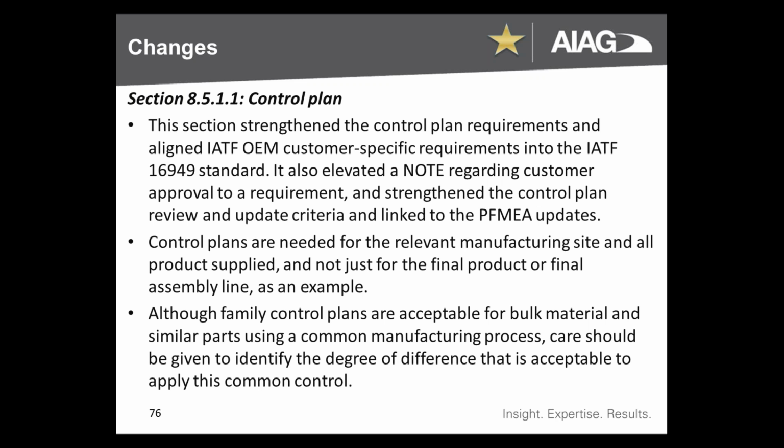Okay, moving through to section 8.5.1.1, the control plan. Here we're seeing many IATF OEM customer-specific requirements now part of the IATF standard. There's been an elevation of a note regarding customer approval to a requirement, and a strengthening of the requirement that control plan review and update criteria should be linked to PFMEA updates.